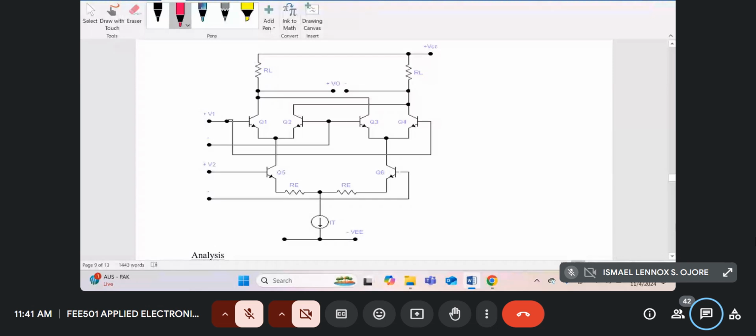So for example, supposing when all the input voltages are zero, maybe 2 milliamps was flowing through the collector of Q1 and 2 milliamps was flowing through the collector of Q4, say. I won't consider that current. I'll only consider the dynamic currents, which are due to the signals to be multiplied.